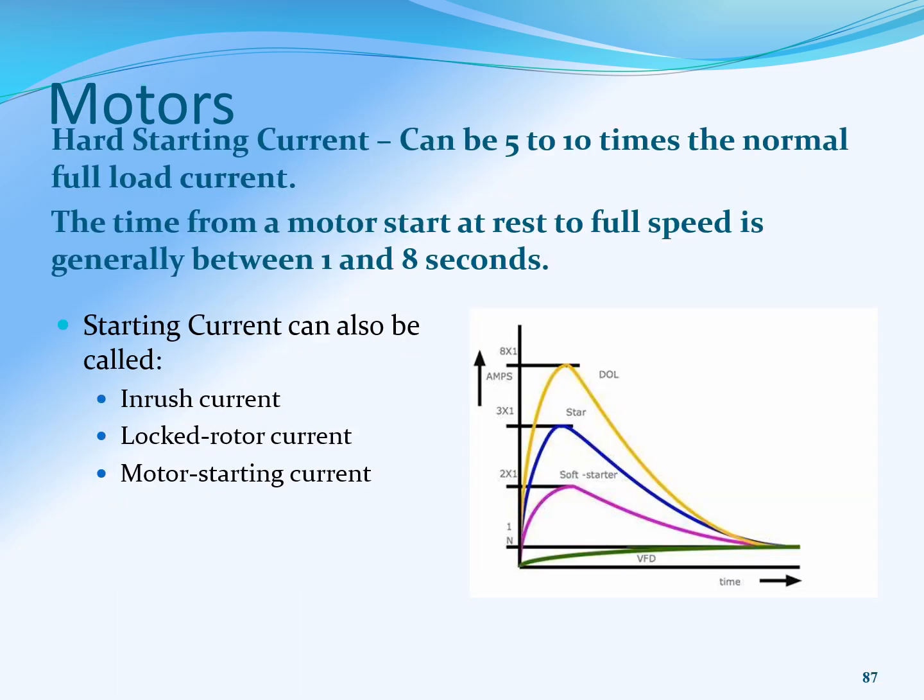Another thing to take into consideration, obviously, is this inrush load, or current. As current is applied to the motor, a lot of times you have to apply 5 to 10 times the normal operating current in order to get it started. You need this high torque in order to take it from a rest into full speed. And the time for it to go from full rest to fully operating at its normal set point could be between 1 and 8 seconds.